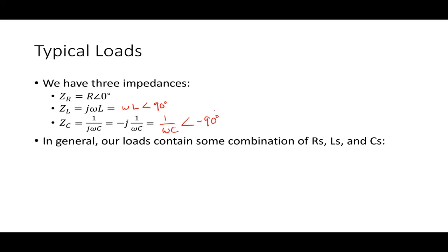In general, our loads aren't just a pure resistor, inductor, or capacitor. In general, there's some combination of the both. Now, one thing I will say is in practice, you almost never see a pure L or a pure C because they don't really do anything. They just basically take in energy and give it back, take in energy and give it back. Most things that I have, like motors, heaters, lamps, computers, really are primarily resistive, but we always have some element of L's and C's hanging around, particularly if we have motors, which are a lot of the large loads that are out there in the world.